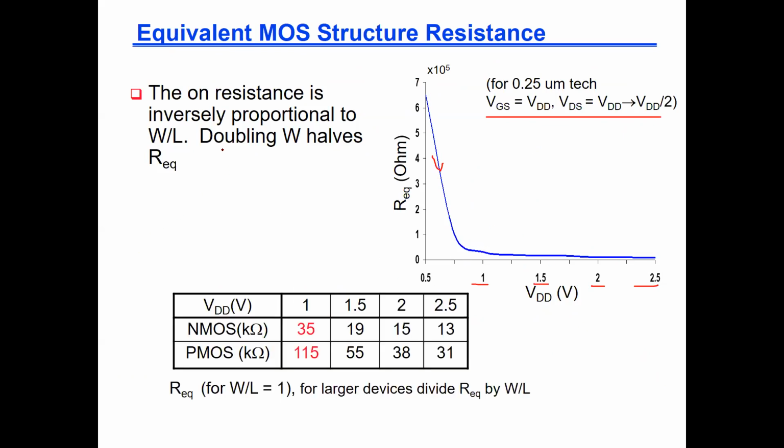And he's saying we can give you a table for the NMOS and for the PMOS equivalently for some typical transitions. For example, VGS equal VDD and VDS going down from this value to this value. But note that the values will change, these averages that you will calculate will change with VDD.